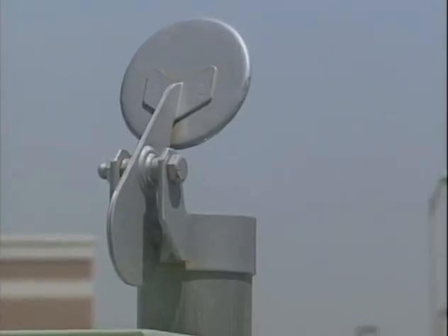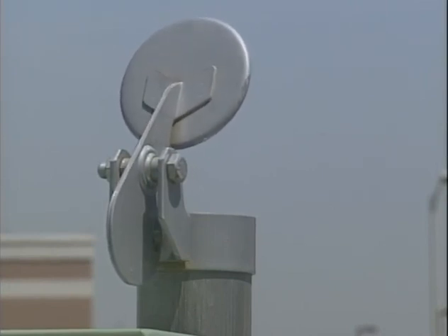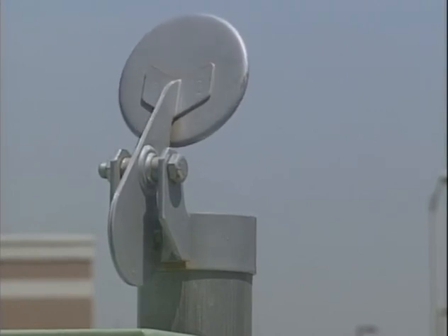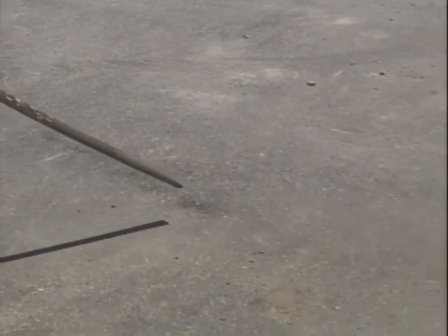Exhaust fumes can cause sickness or death. If it is necessary to run an engine in an enclosed area, remove the exhaust fumes from the area with an exhaust pipe extension. If you do not have an exhaust pipe extension, make sure you open the doors and get outside air into the area. Never breathe the air discharged from the air compressor. Exhaust fumes may be ingested into the compressed air system.